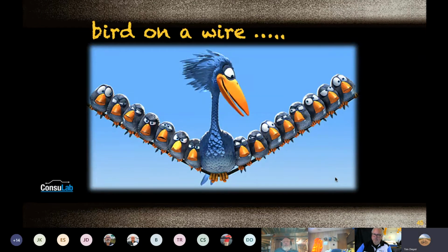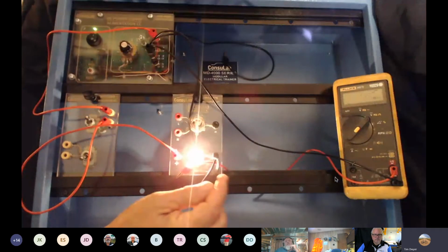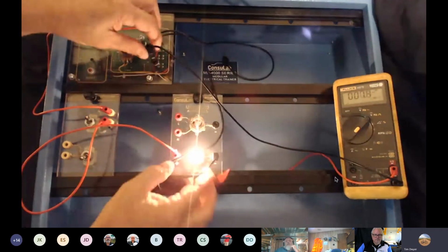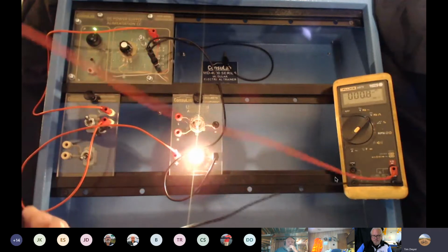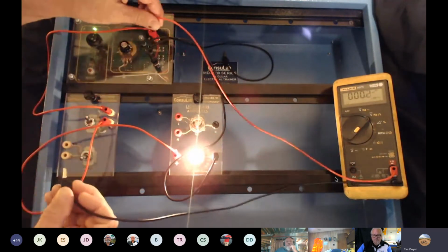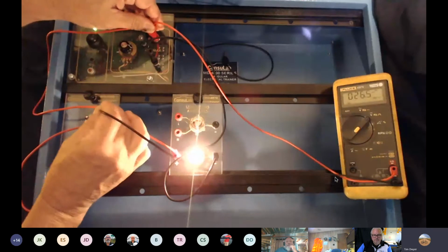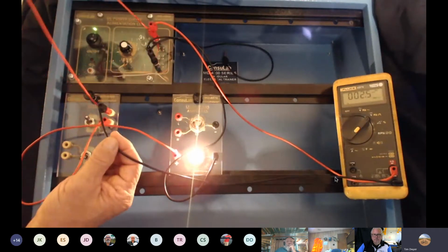Let me show you something else here real quick. Let's go back. That was ground reference. If I found a problem, I would pick up both my leads and actually start walking down the circuit and trying to figure out where it's at by comparing these two leads on sections of the circuit. So I'm going to do almost the same thing I did just a minute ago, except now, instead of getting a voltage reading, I'm going to check this wire with my meter.